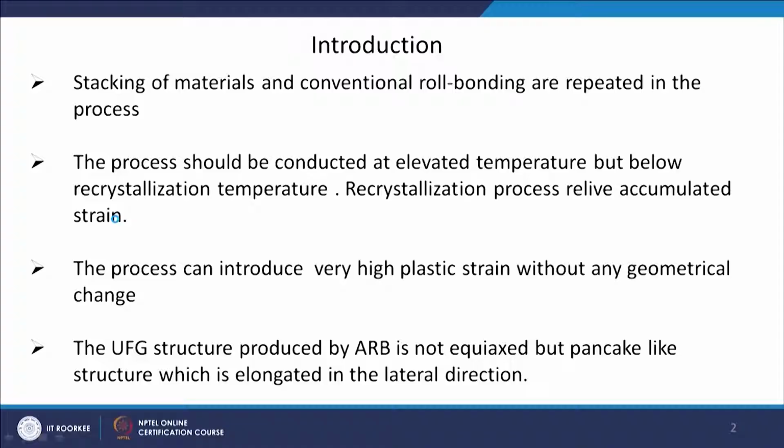First, do some mechanical removal of the material. Also, you want to increase the roughness of the sheet so that it can create more area for the bonding, as well as there will be cleaning processes. So, it has its share of complexities in terms of sample preparation or surface preparation. So, it is like conventional bonding repeated continuously.